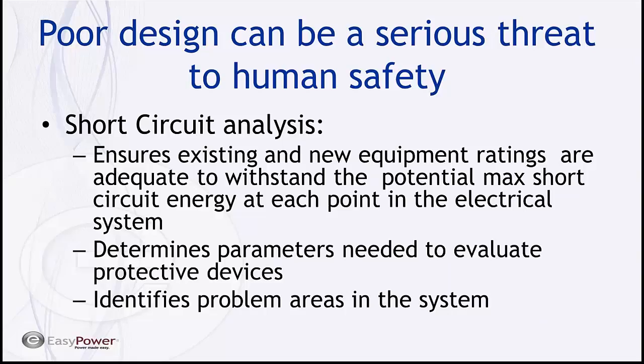So that's the function of the short circuit analysis, is to ensure that the existing and new equipment ratings are adequate to withstand the potential max worst case event that a short circuit would pose within the electrical system.